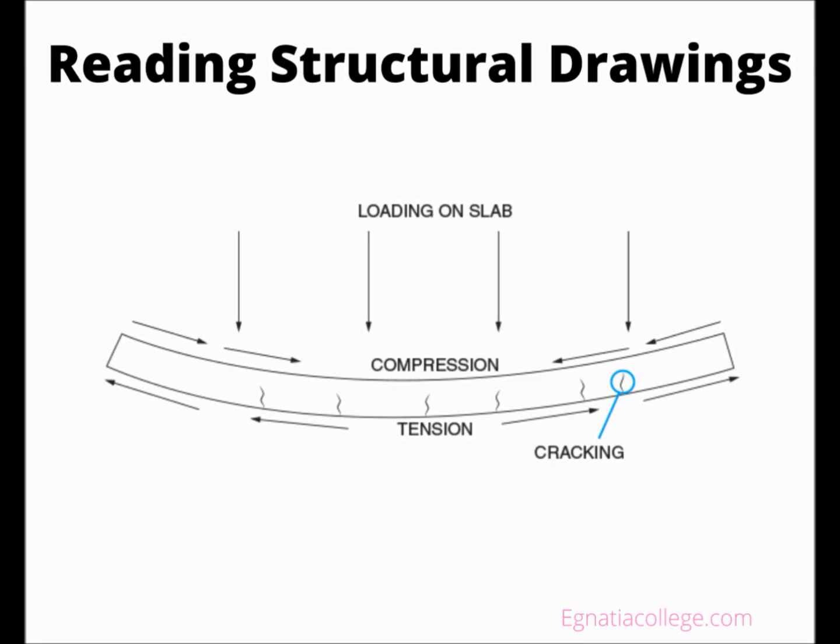The foundation and framing plans have schedules, such as the shear wall schedule, notes, such as general floor framing notes, and other miscellaneous notes. They also have other plan views, but are titled Elevations B or C, not to be confused with architectural elevations. Schedules use different shapes, such as a triangle or hexagon, to denote a reference to different schedules, just as in architectural drawings. The reference to details is the same as in the architectural drawings: a circle with the detail sheet number on the bottom, and the detail number on the top.